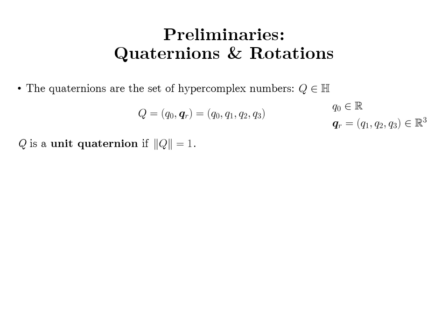In this paper, we use dual quaternion representation of the object and end effector poses for motion planning. Using dual quaternions is computationally more efficient compared with using transformation matrices. Quaternions are the set of hypercomplex numbers. The quaternion Q can be represented as a four-tuple where Q0 is the real scalar part and QR is the imaginary part.